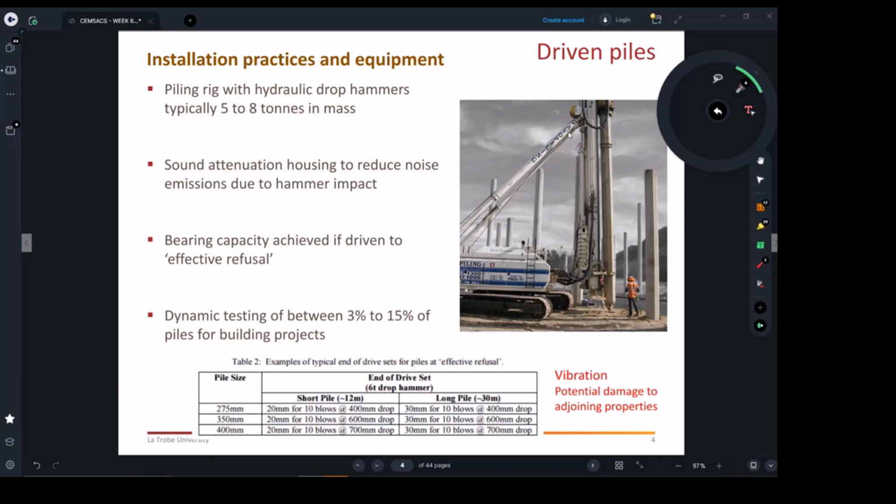But basically, these machines have the ability to do the lifting for the piles. So you see, this is again a road. It's for constructing roads. As I said, this is very soft soil for a couple of meters. The solution here is to nail down, to reinforce the ground, so they keep hammering piles in over specific distances, then they're just going to build a suspended concrete slab. Then on top of the slab, they're going to put the asphalt.